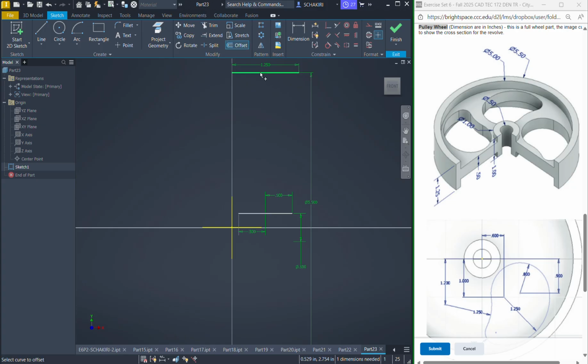We're gonna use the offsets. So here it is 0.25. How do we find this? We have the big exterior circle with a diameter of 5.5, and the inner big circle has a diameter of 5, so 5.5 minus 5 is 0.5 divided by 2 for each side, so it's gonna be 0.25. So we're gonna offset this one by 0.25.